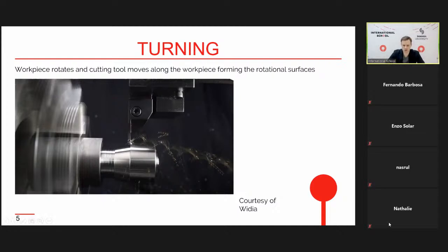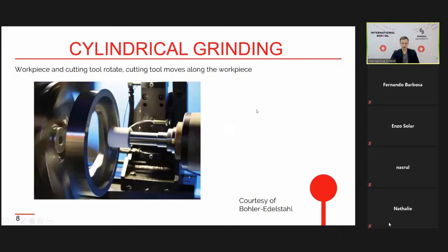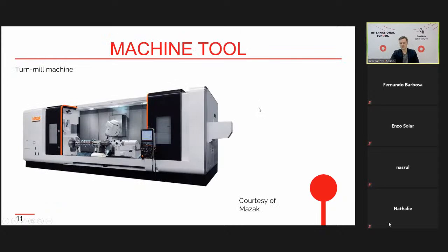But when we need to move in 2 directions simultaneously to form, for example, a conical surface, we cannot push 2 buttons simultaneously, or if we push them, it means that the angle will be 45 degrees, but this angle is rather 30 degrees, approximately. That's why to control this movement, we need special control for the machine. This control is called CNC, computer numeric control.